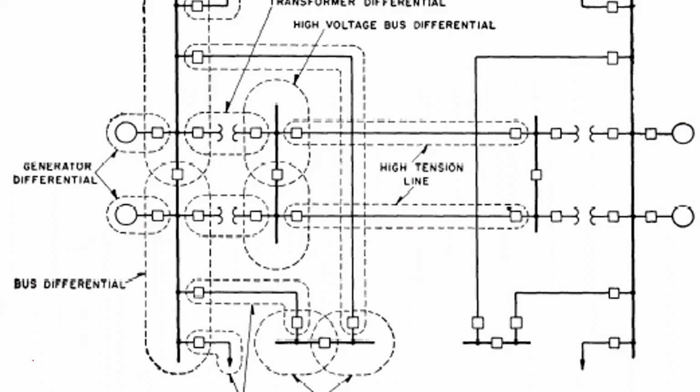Okay. All right. So back to what Mr. Clark was asking. So I'm going to use again this generator as reference. All right. If I have a fault on generator A, Mr. Clark, this breaker that I'm going to call A star is the breaker that should open in order to clear or to remove the generator from service.